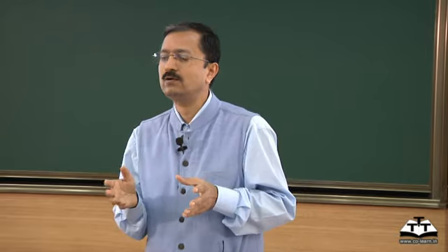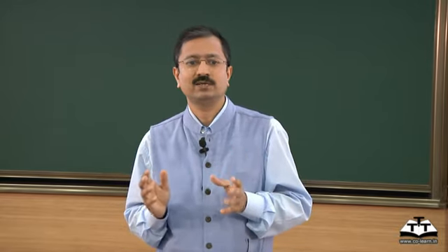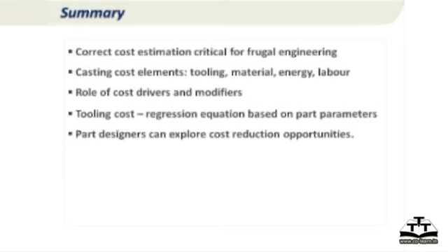If you have the part CAD drawing, you can estimate tooling cost in a second. But the idea is to use cost estimation not so much for quoting or negotiation purposes, but more as a DFM tool. A designer can use this to choose between two design alternatives. Of course, you can also use it to compare two different methoding alternatives, to see which is the more economical one.